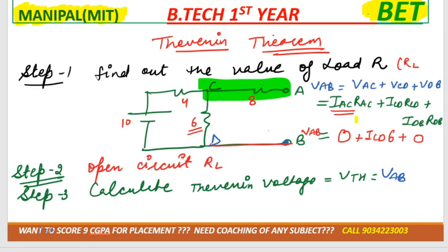If you know the value of ICD, will you be able to get the value of VAB? And how will you get the value of ICD? By using mesh analysis. Whenever you need to calculate the current in the Thevenin theorem, you need to use mesh analysis rather than nodal analysis. That would be easy.